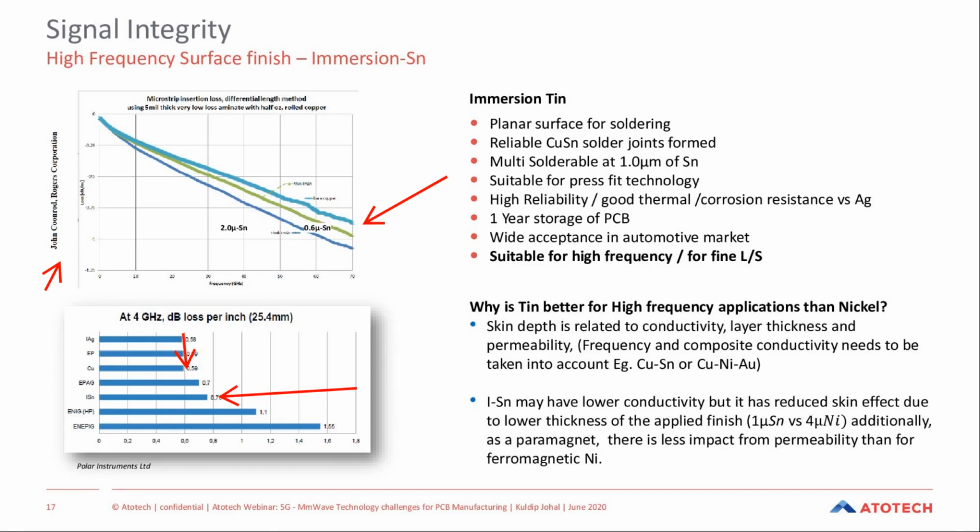However, regardless of that, you also have to consider the tin. If you take a circuit that is open to the corrosive atmosphere, whether it be tin or silver, you have to think about byproducts and corrosion products that are affecting conductivity. Just like tin will not stay the same, silver will not stay the same. Once the silver is no longer pure silver, you will alter the conductivity, which is then going to alter the performance of the finish.